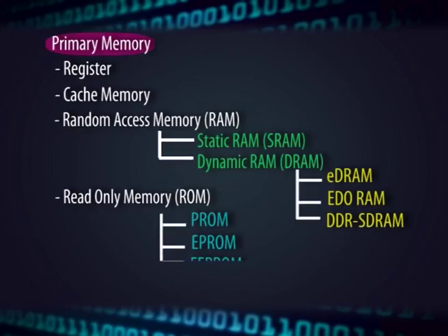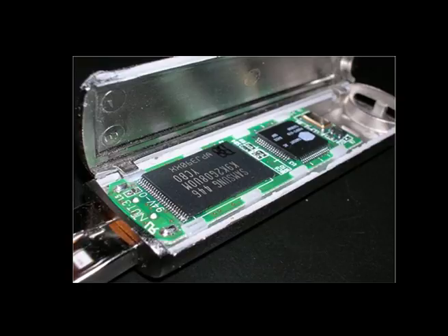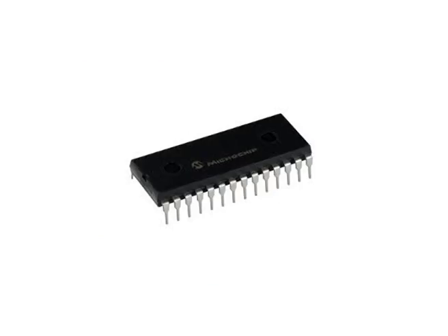The next type of ROM is EEPROM, that is electrically erasable PROM. It is used to store small amounts of data that must be saved when power is removed, for example calibration tables or device configuration. Internally, they are similar to EPROMs, but the erase operation is accomplished electrically rather than by exposure to ultraviolet light.